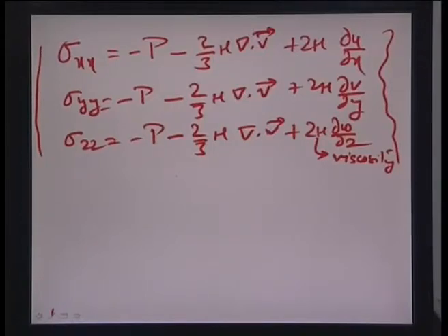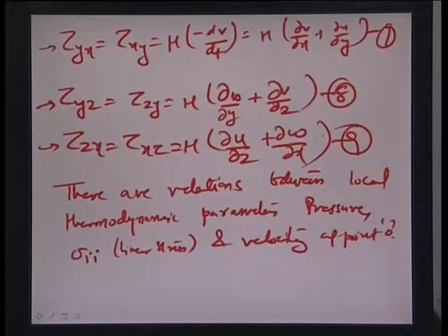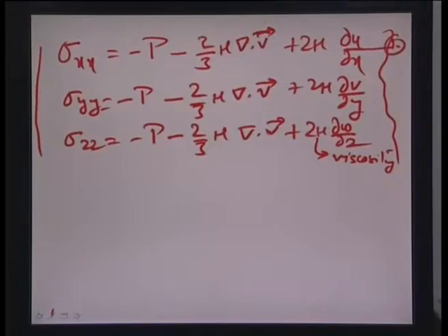So these relationships, if we assume them and do not derive them, and then put this back along with the stress vectors that we have seen before, the shear stress vectors here in equations let us say 7, 8 and 9, we finally get a form of the Navier-Stokes equations which under incompressible flow conditions are assumed to be true. So the final form again, I am going to write from here by substitution of these shear stresses and the relationships between the different principal stresses. Let us call these equations 10, 11 and 12 respectively.